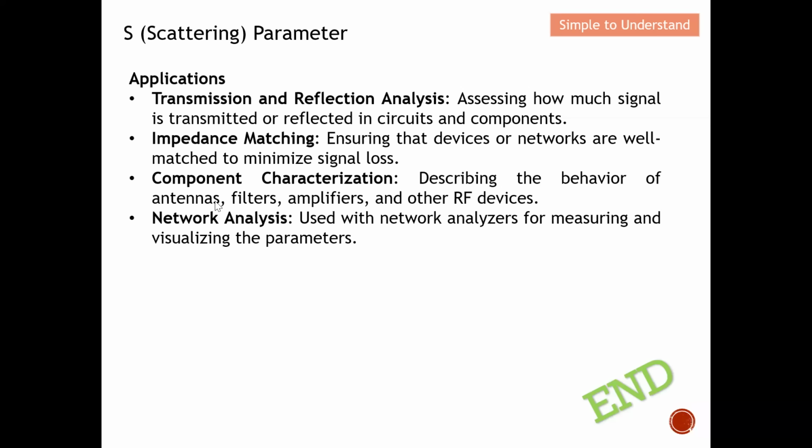The key application of S parameters is the vector network analyzer. I believe this equipment is highly used. If you work in an RF environment, you will always use a vector network analyzer. It measures, for example, the amplitude versus the frequency, or the phase versus the frequency. With the S parameters, you will be able to categorize the components.